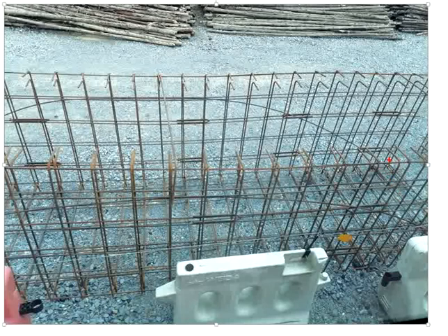You can imagine that there will be pile foundations here. Assuming the entire concrete drain is simply supported onto the foundations, this will form a condition as if a truss, an imaginary truss condition, and there will be a region of compression, which is known as the compression strut. I believe by having the reinforcement here, this will strengthen the compression strength of the concrete at this region. Correct me if I'm wrong, feel free to comment.